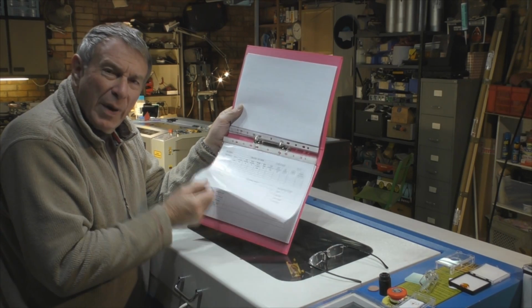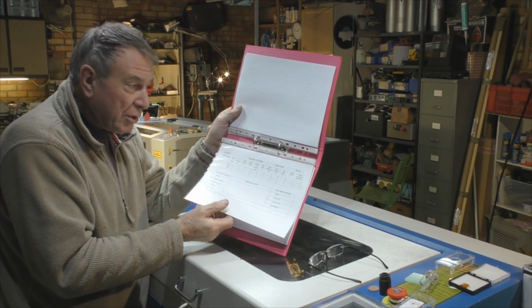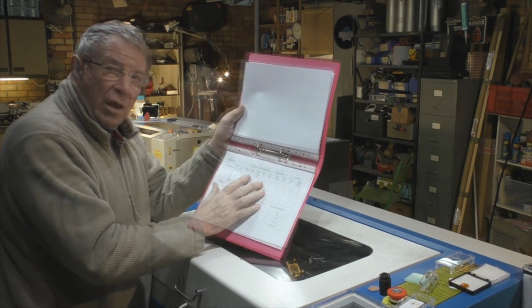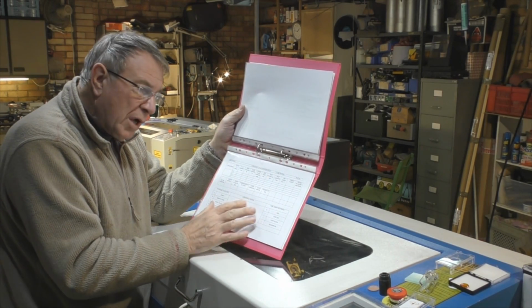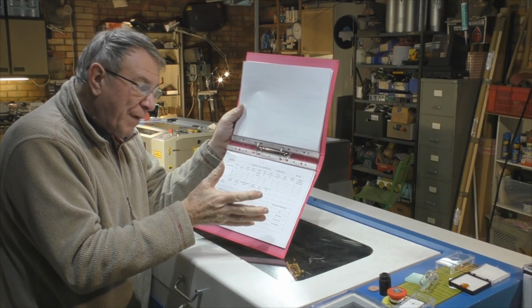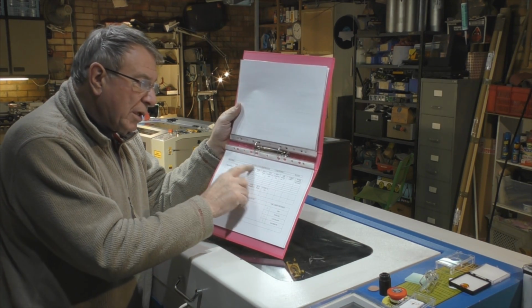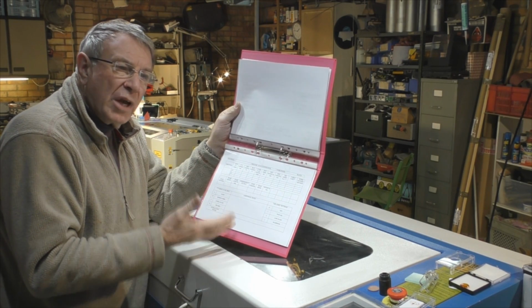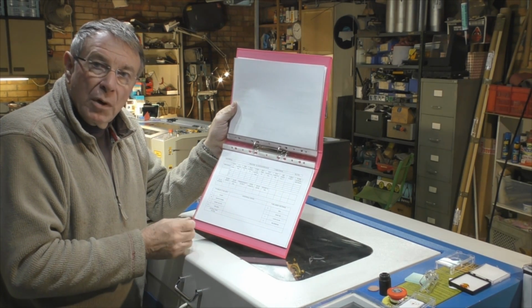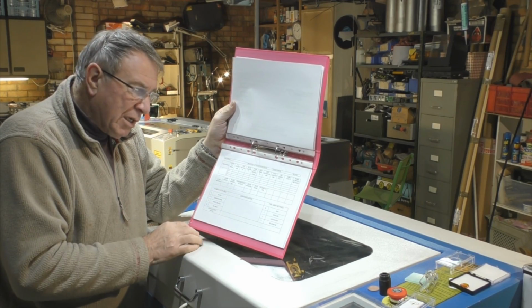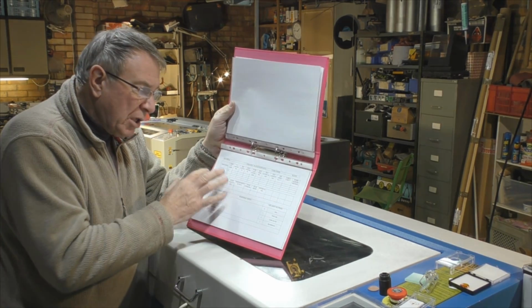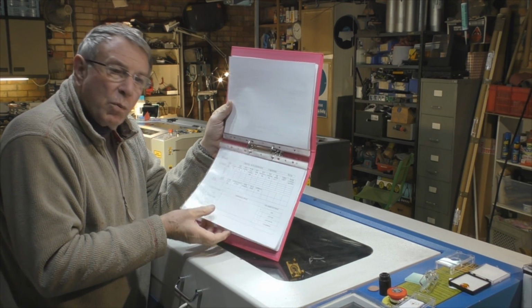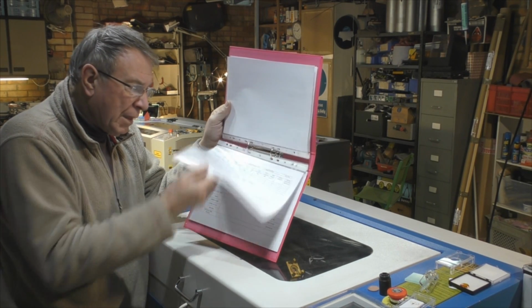Dot mode is a very powerful technique which we shall get onto eventually. We now move on to engraving. Engraving, one word, but many facets. First of all, we've got continuous engraving, the sort of engraving that you get when you generate characters, for example, within RDWorks, text. You zip backwards and forwards and you continuously engrave the text in a scan mode. That's one type of engraving.